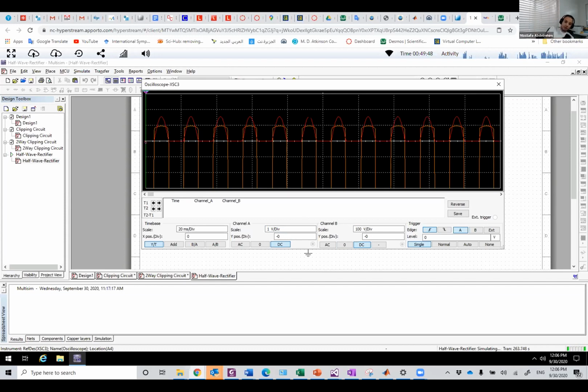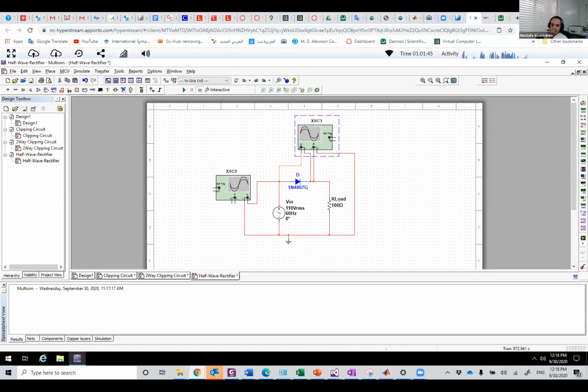So the output on the resistor, this one, should be 155.5 minus 1, because we measured now that the clipping voltage is the VD on of the diode, and it was 1, not 0.7. Okay, so guys, do that now, and you have again 10 minutes.